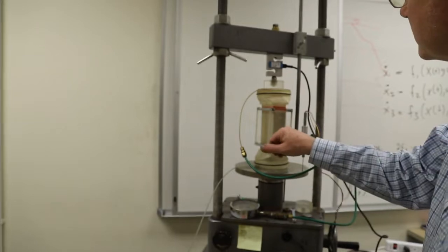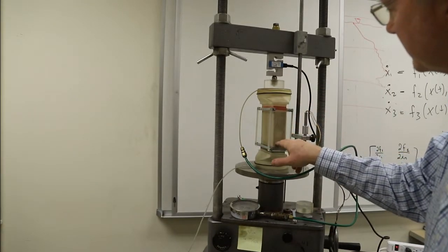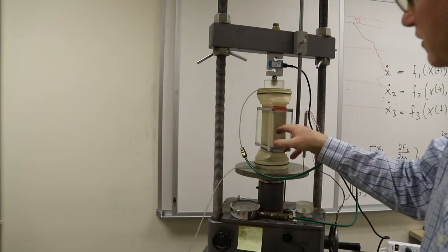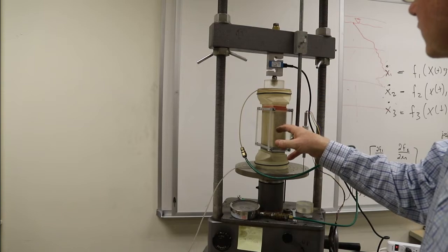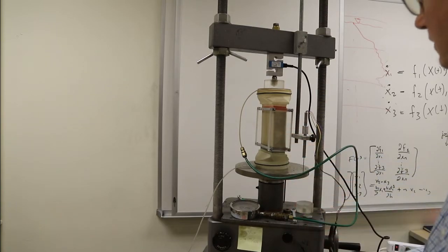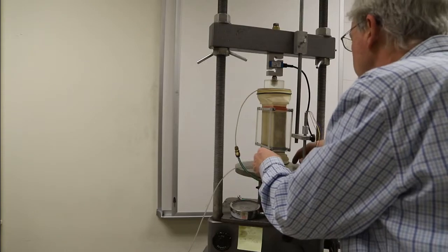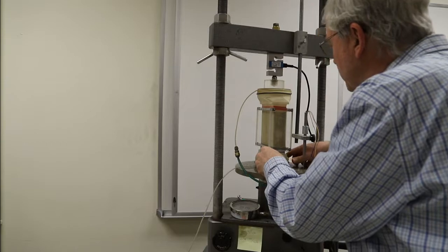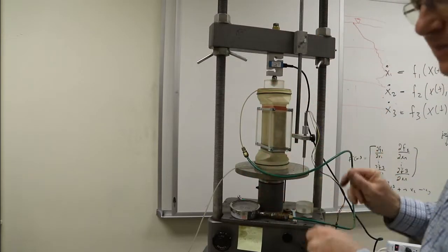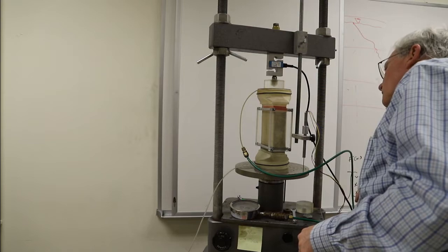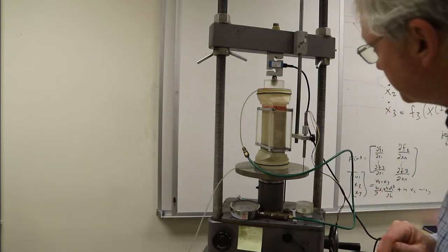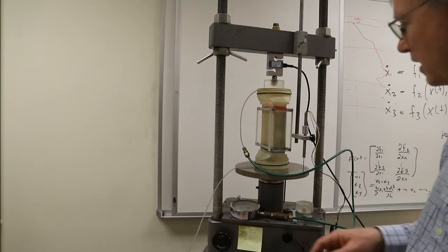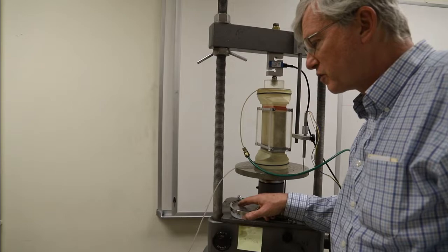Alright, oh, you can even see where that squeezing of the grease has actually highlighted the color change here. I think the darker color is where we have contact, good contact already between the membrane and the plate and the grease. Oh, and I'm noticing here at the bottom, I don't want the tie rods touching the caps either, so I just adjusted that. Alright, we're going to shear it at the same rate. We want to check our confining stress, make sure it's what we want.